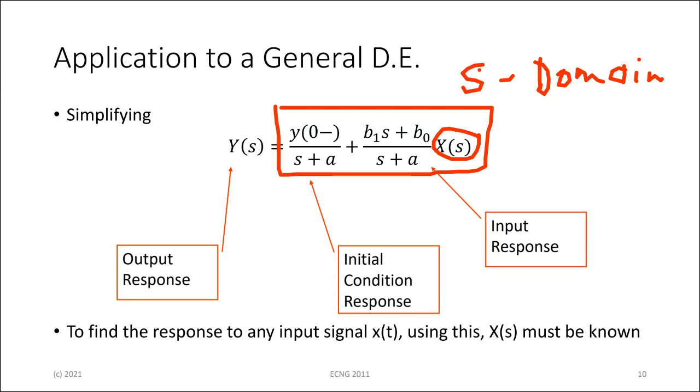And there's a little warning here: in order for this to work, you must be able to find the Laplace transform of x. Certain things, like last week when we discussed piecewise continuous signals, if you have a set of piecewise sinusoids or cosinusoids or exponents, sometimes it's very difficult to calculate X(s) in a situation like that. So these things work within reason.